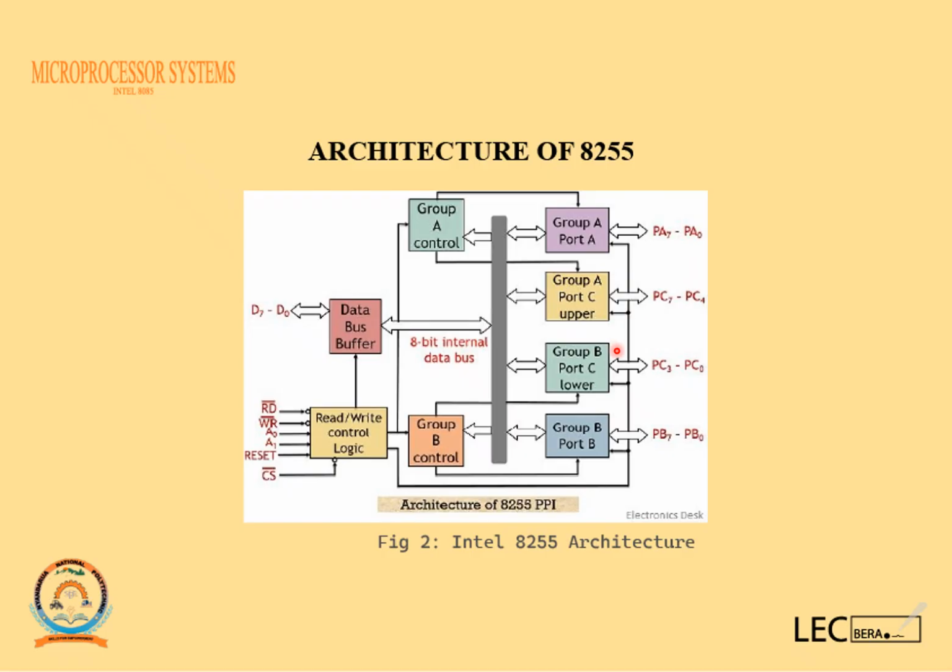The extra pins in group B are going to form part of the pins in port C, but these pins are going to occupy the lower part. I think this is just designed to utilize the IC well, and to make sure that we don't have a lot of excess pins. I think that is the reason why they did that.